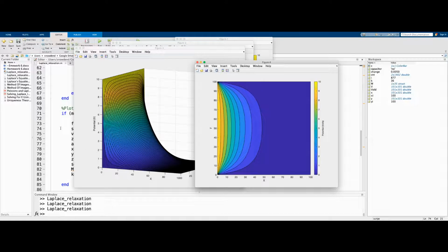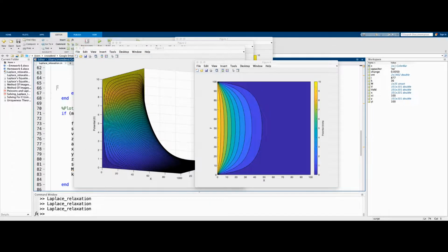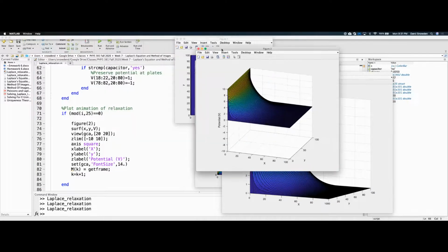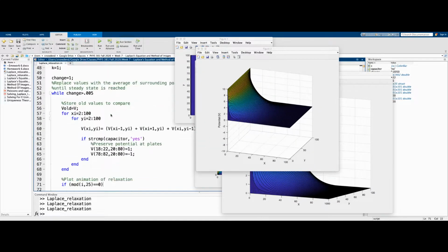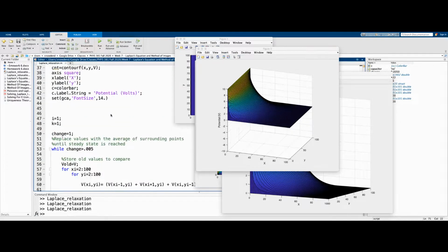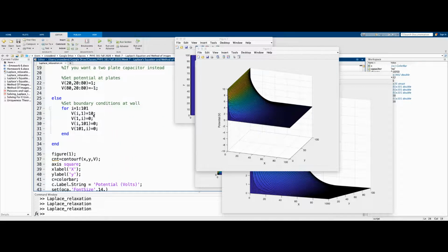So let's just make that more fun and solve it again. Let's go back here and change the code a little bit. I'm going to go up and instead of just setting the potential to be equal to some fixed number of 10, I'll let it equal something sinusoidal. So how about something like that? Okay, so now it'll have a little bit of waviness at the border. And I don't know, maybe at the other side here, I'll have it be equal to 2 or something like that. Okay, let's go ahead and let the program solve that particular configuration with those boundary conditions.